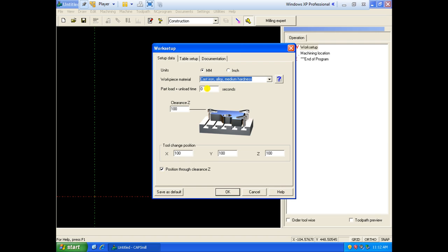This is the loading and unloading time. The loading and unloading time is the time between loading the next raw material and the previous, already machined part. It is a non-processing time, like an idle time. It should always be minimum so that we can get more efficiency in manufacturing. As far as possible, we need to minimize this. Let it be 60. This is 60 seconds, that is 1 minute, in terms of minutes.